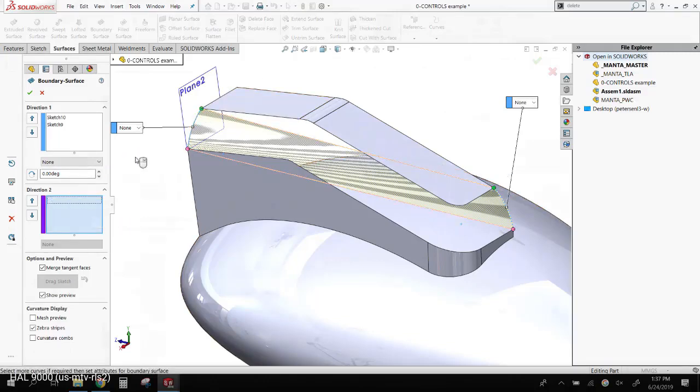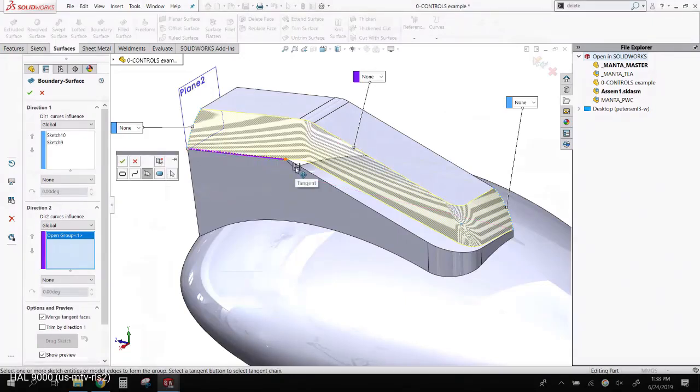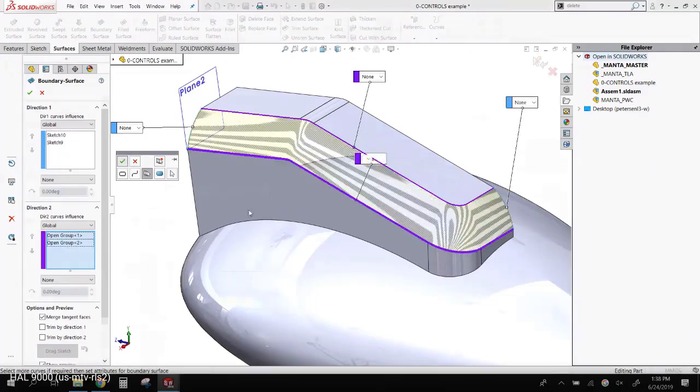Let me clear selection. When you've got a selection box like this in SolidWorks, if you right click, there's a choice to do a selection manager. What the selection manager allows me to do is I can pick multiple items. Once I'm done with it, I hit the green check mark, it's all one line. So even though it was a composite of a bunch of different edges and arcs and things like that, it ends up giving me one. You can either right click in here, right click on the screen. If you see one of these marks, it's recognized the tangency, and that's nice. So it picked that whole edge for me since it was all tangent. And I can just continue.